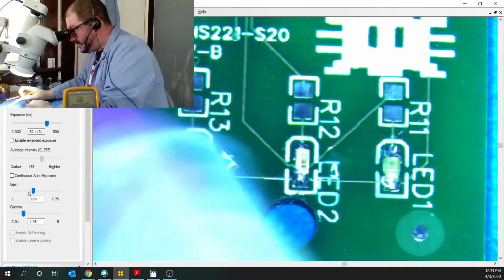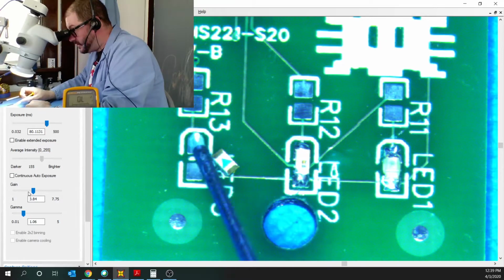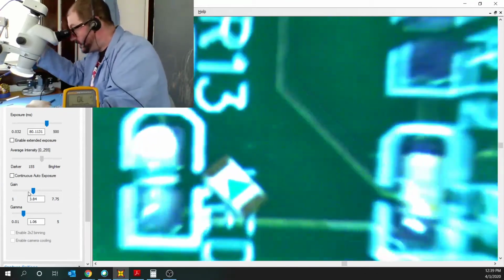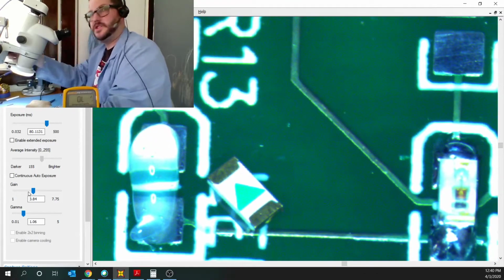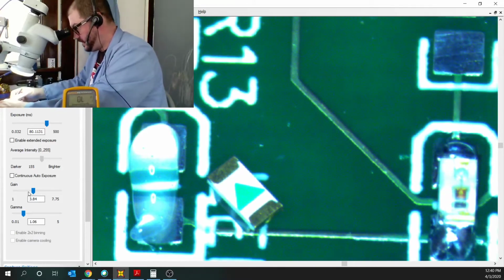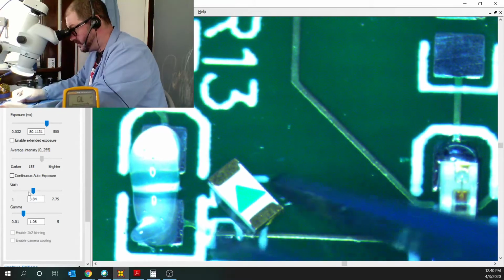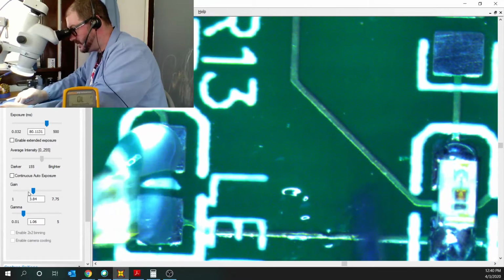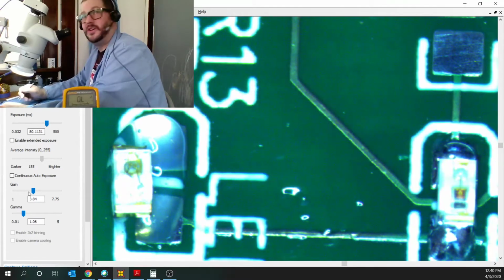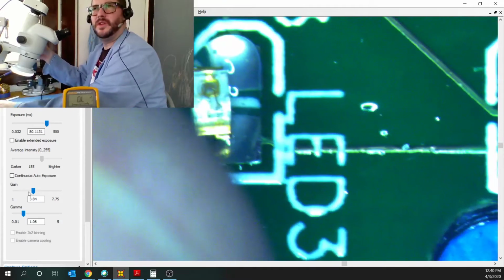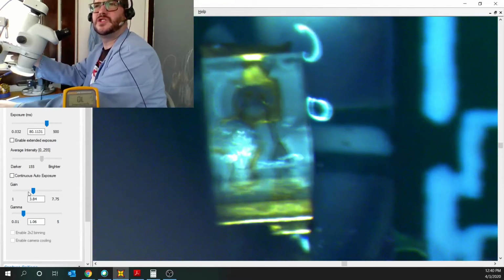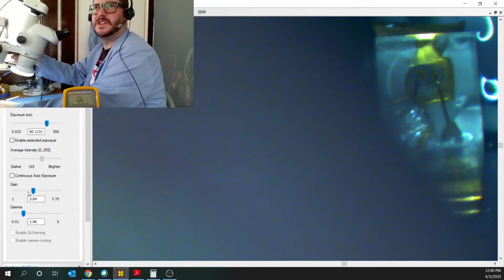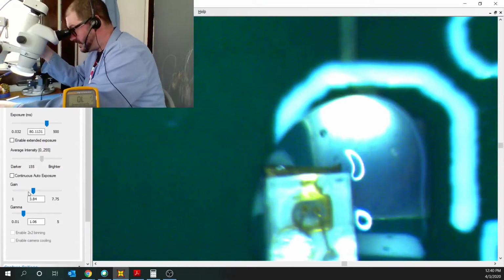And let's start the attaching process here for LED 3. I'm going to put a generous amount of fluxing agent down. You'll see here in just a little bit as I flip this guy over and stick them into some of the tacky flux, which happens to be all stuck down to this board here. There you go. And if one were to look very carefully at this LED, there are actually two wires on the inside that attach to the die that's on the inside part of the LED. It's how I have an idea.